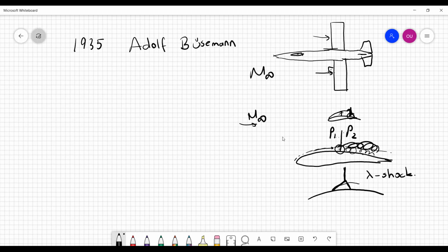So in addition to having the static pressure increase, which contributes to the wave drag, we have basically separated flow after this. And if your control surfaces are within the separated flow, they are ineffective. That's why the crash happened, the crash that the guy was talking about in the video for the P-38 during a dive. Because of this, it had a straight wing.